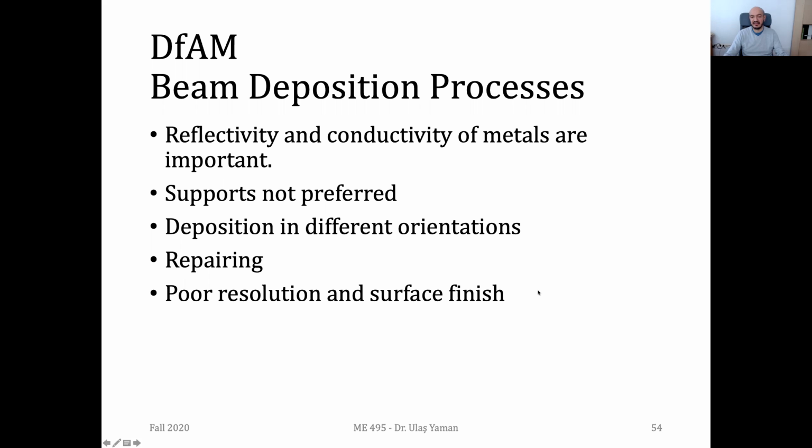The surface quality is again one of the worst, since we have powders moving all around. We have molten pools. Some powders will actually be trapped in these molten pools, and once they are solidified and cooled, we will have some wavy surfaces, and this will result in high surface roughness values.